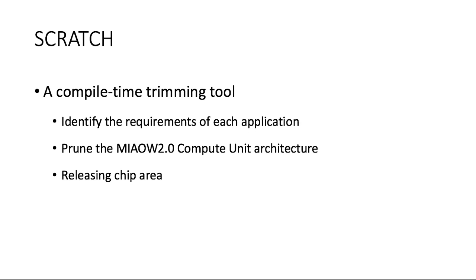A compile time trimming tool that is able to identify the requirements of each application and prune the MIAOW2 compute unit architecture to the application-specific needs, releasing chip area for adding more compute units, cores, and thus computational power to the parallel reconfigurable architecture.